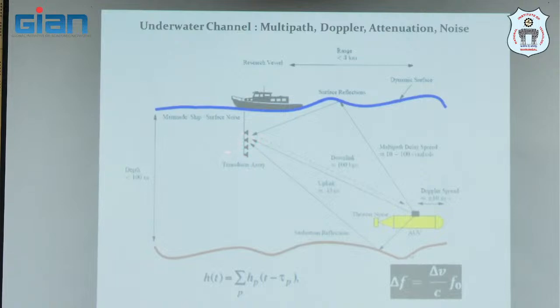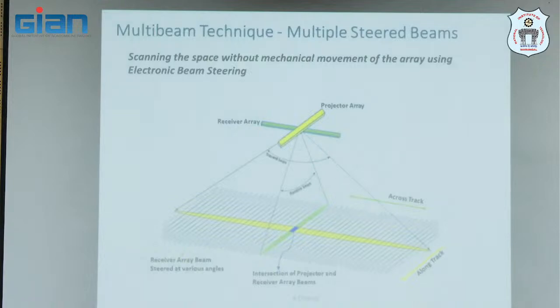In underwater communication, if we want to recover the data, then we have to reconstruct the signal at the receiver. Reconstruction means the distortion should be less, so we need to choose a suitable filter which will have less distortion. That is one inference. And also we can use more than one sensor on the receiver side, which will improve our SNR. This is another inference.